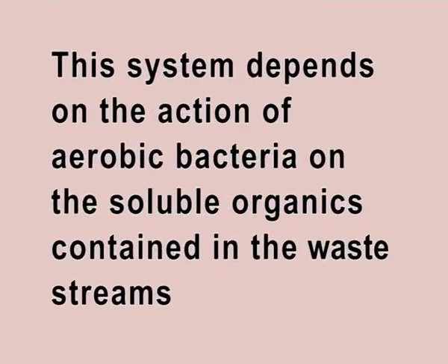The stabilization and pond treatment. A common practice for improving the effluent treated in the aerated lagoon is the use of stabilization or polishing pond system. This system depends on the action of aerobic bacteria on the soluble organics contained in the waste streams. The organic carbon is converted to carbon dioxide and bacterial cells.